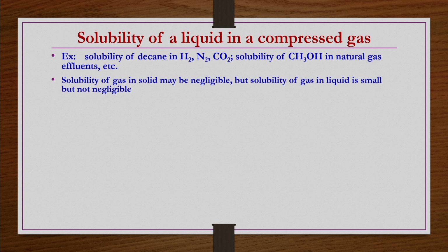Be careful, the y2 relation we are going to derive in this case is different from the y2 of the previous case. The previous y2 accounts only for transfer in one direction, from the solid to the gas, but here y2 accounts for transfer on either side, solid to liquid and liquid to solid. So, this expression is going to be different and has to be obtained by a trial and error solution, whereas the previous one was a straightforward substitution if you know phi2, phi2s, etc.